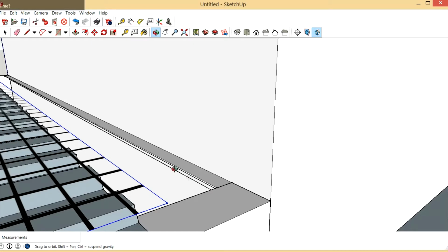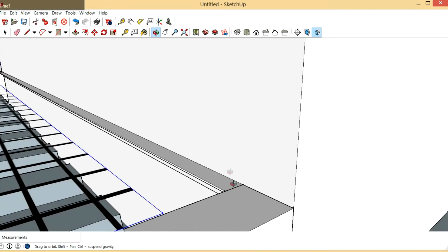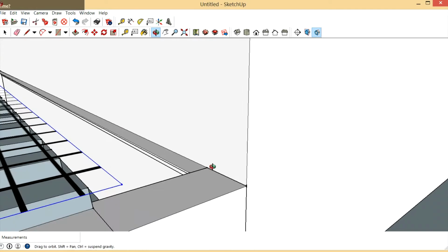Unless you can bolt this into good structure, whether it's your foundation, you'd want through bolts going all the way through. If it was concrete block, you don't want to play around with this. If you're questioning that at all, just go ahead and fill this thing up with gravel. I was just trying to give you an alternative here. But in any event, let's create a